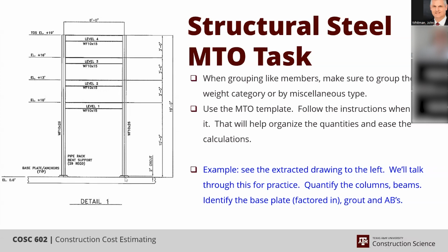Okay, that makes sense. Thank you. Yeah. And one additional thing is that if you notice here, it tells you 2-inch grout spacing. If you go back to the concrete drawings, it doesn't really say what the thickness is. It's the steel drawings and the equipment drawings that are actually requiring the need of the grout, and they normally will tell you what the parameters need to be.